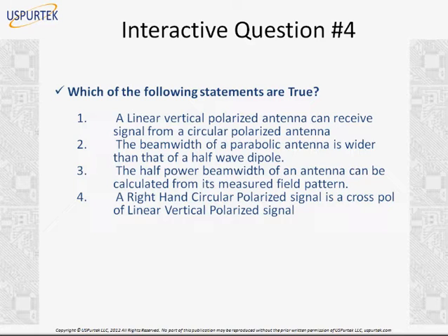We can improve the performance of signal by having a circularly polarized signal, which, of course, is used in satellite communications because there definitely the stakes are high. Your signal is so weak, you must have both components received. But in terrestrial communications, you can achieve acceptable performance with a linear polarized signal. It's only a matter of implementation.